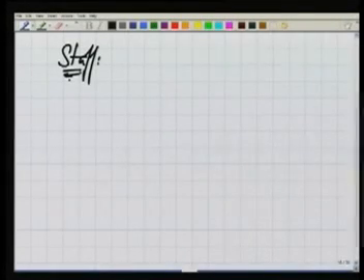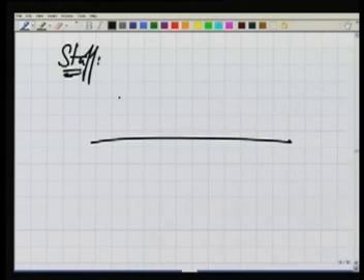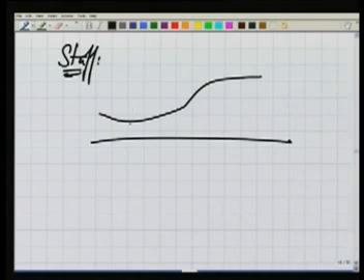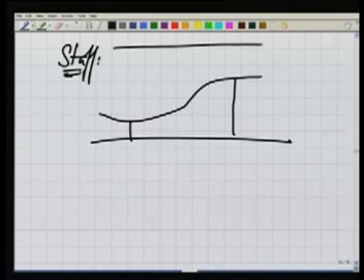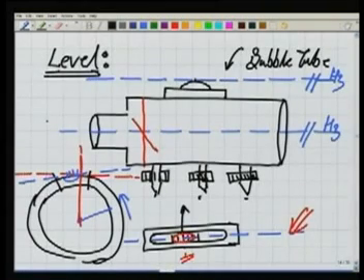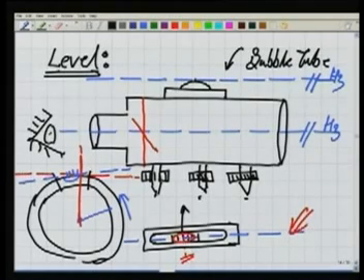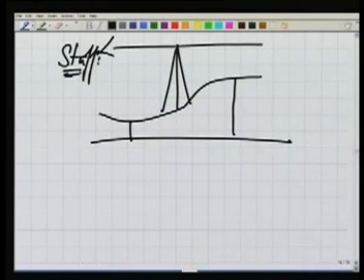Along with this level, one more instrument which is very, very important is the staff. Now what is this staff? As we were seeing how we were doing the leveling, that was our datum, 2 points. We want to determine the difference in height between these 2 points, or their relative RL differences. What we are doing is establishing the horizontal line of sight, or horizontal line, as we know now, and we can do it by level. When we look through our telescope, your eye is here, so you are looking along a horizontal line.